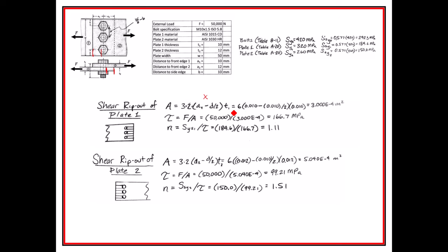And there's going to be 3 of them, and there's 2, right? So there's actually a total of 6 of these areas that are resisting. It's a little weird looking right there. Of course, it doesn't actually work that way, but that's all right. We're following through here just as a means of comparison. We get an area, and we're able to figure out what the shear is going to be right there, of it trying to shear away through there.